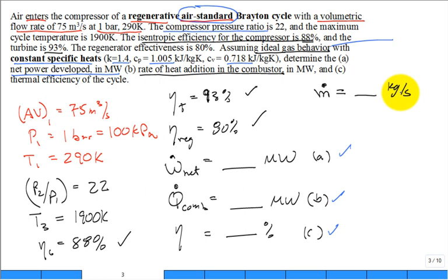And if I could get that to calculate W_net, isn't that going to be the mass flow rate times the specific net work per unit mass going in the loop? Yeah, that's what that's going to be. And this W_net is the sum of the W column in my table of energy transfers. Hopefully that makes sense.